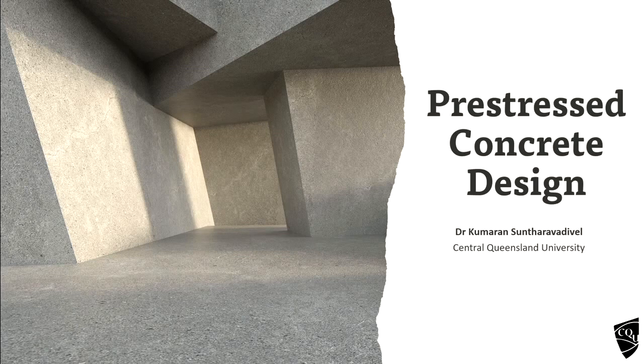So what we did in reinforced concrete design, we looked at the tensile zones, because the concrete can't take tension, and we provide steel reinforcements or steel bars, so that the steel bars take the tensile force or tensile stress while concrete takes the compression.